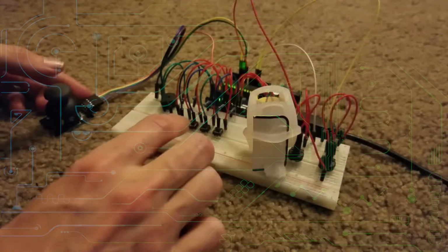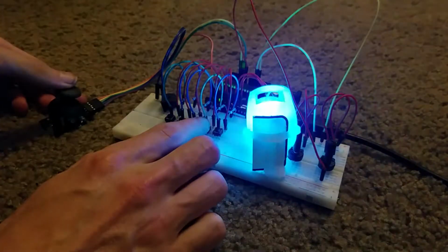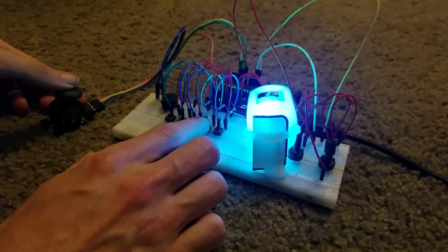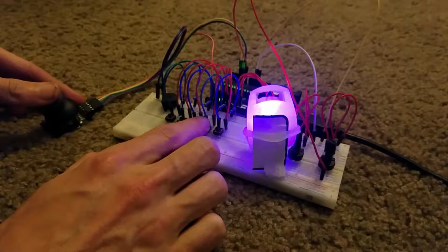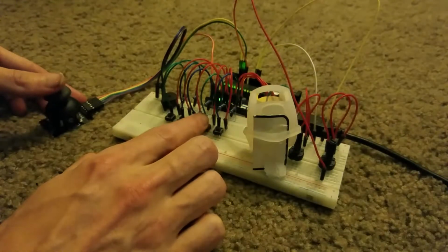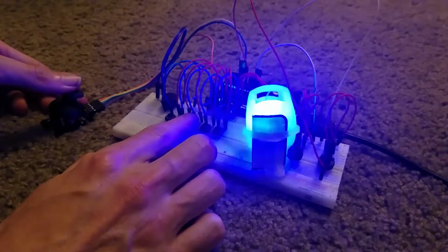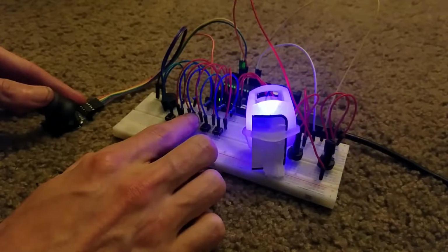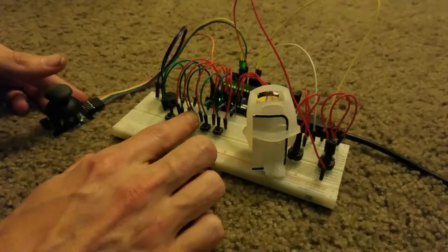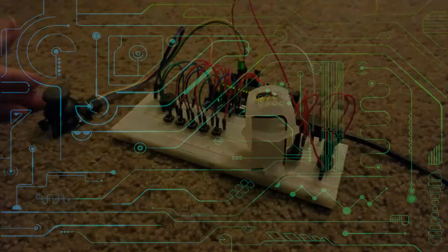Now that we have xmod, we can go into playNote and add xmod to the frequency that tone plays, as well as the frequency that's being the input to our pitch to RGB function. Caveat is the pitch will only change once the note has been played and it goes on to the next note. So it isn't an actual pitch bend, but this is what I've figured out. The closest you can get to a smooth change of tone and color is to turn the potentiometer up in resistance so the delay between notes is very fine.